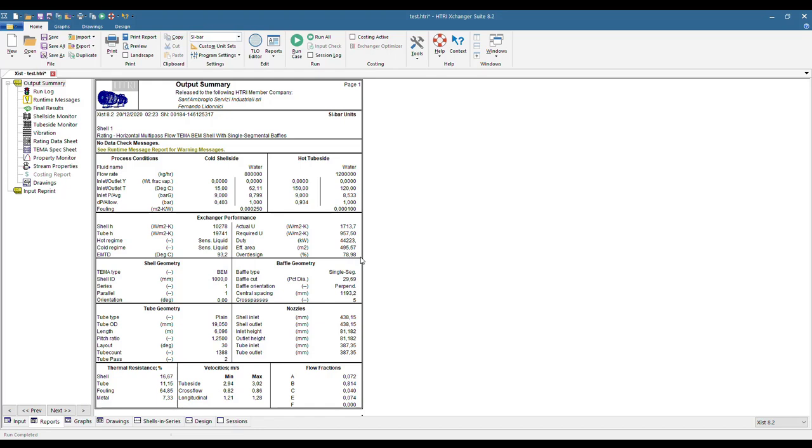Reduce the tube bundle. To reduce the size of the tube bundle would mean to come out from the specified limit for the pressure drop, because the exchanger has already 2 tube passes.